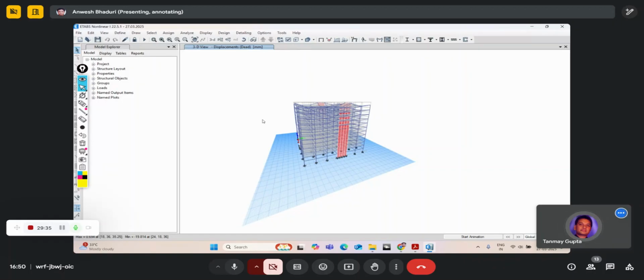But if I do it with the scaling on the load combination, I don't think the results will come the same on the base shear value. If I apply the modified RS after applying the scaling factor and then do a combination with RS versus doing it with the static load case, there will still be, I guess, not the same result of the base shear. I'll have to check.